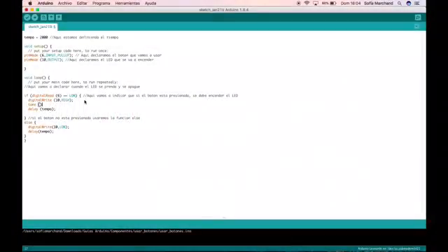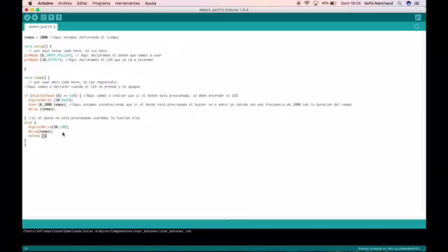Here's the explanation of how the buzzer is used. We're going to use the same program as we used the last time. After digitalWrite, we're going to write tone with the numbers 0, which means that the buzzer goes from 0 to the frequency of 2000, and then we're going to write a tempo to indicate how much time it stays on. After else, we have to write noTone to indicate that there is no tone in that part.